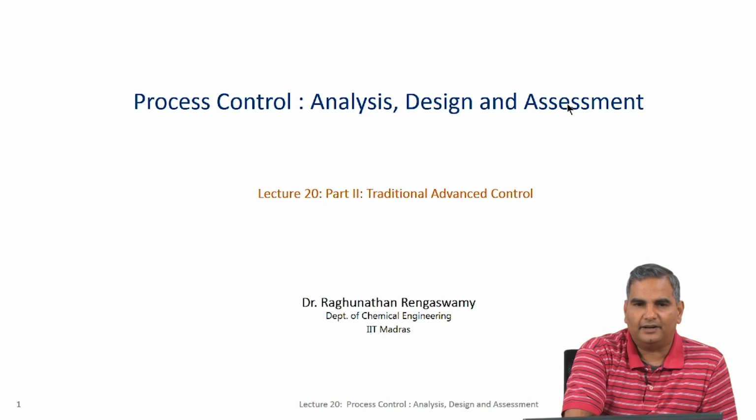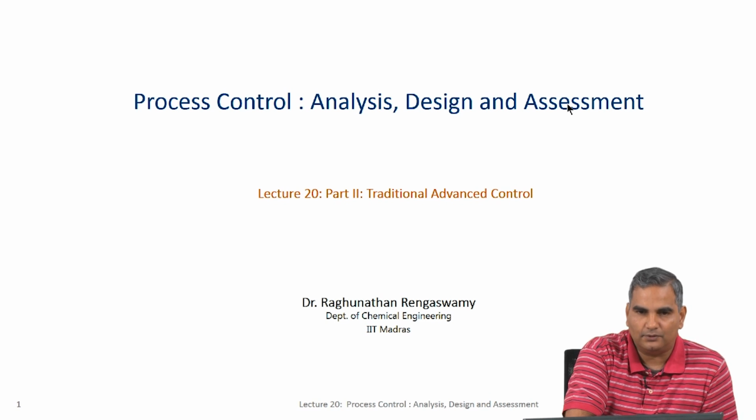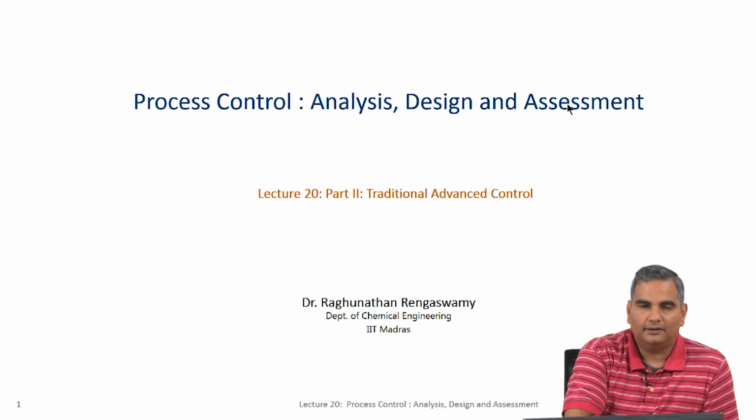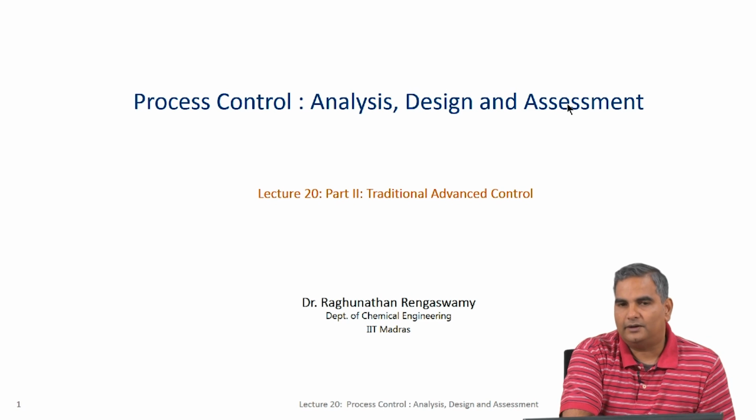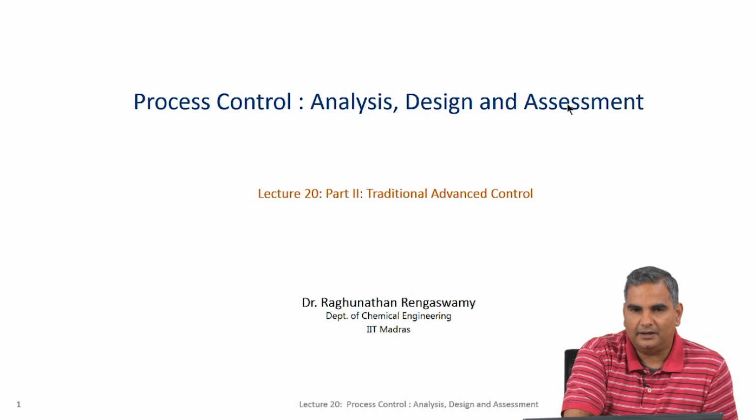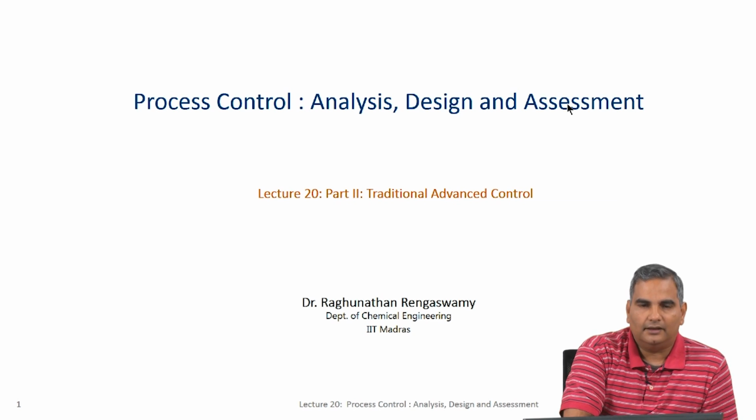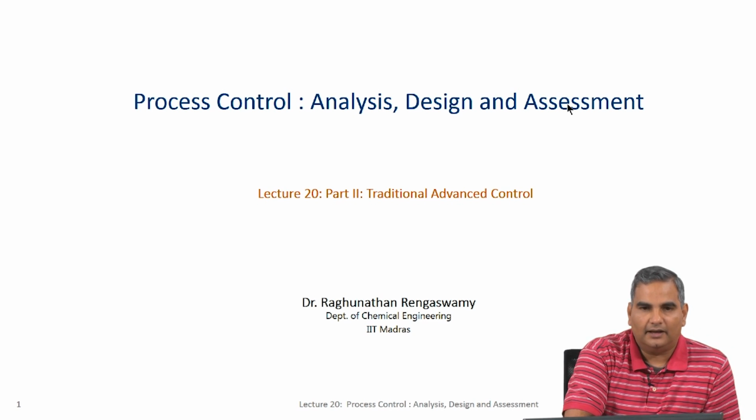And that is also very nicely seen in the direct synthesis approach, and there I said, if you remember, the controller formula in the direct synthesis approach is 1 over the transfer function of the model GM times G desired divided by 1 minus G desired. Because we are inverting the process model, any right half plane zero in the process will become a right half plane pole in the controller. So, if you want to get an ideal response, whatever you desire, then that would mean you will have to have a controller which is unstable, and that is never good.